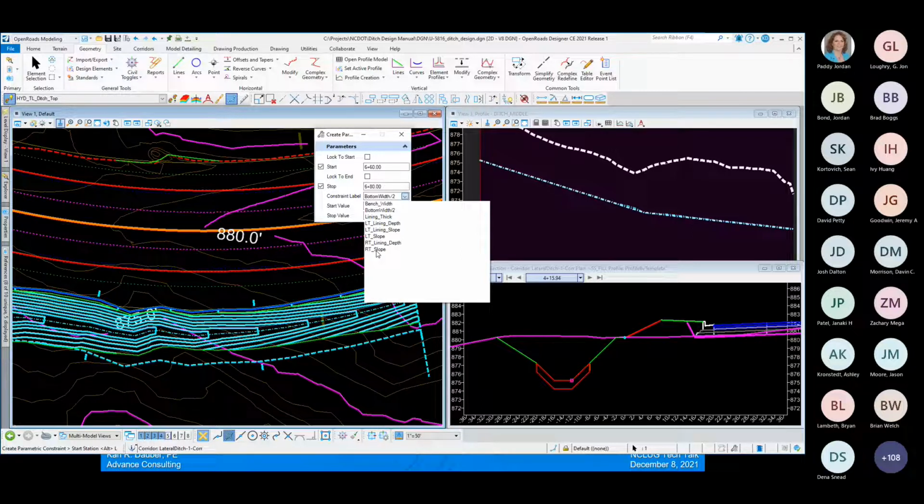The special cut ditch. If the special cut ditch is remaining with the roadway engineer to model, does the ditch lining need to be reflected in the roadway template? I think the answer to that is yes. The video that I have on my YouTube channel shows how to create the ditch controls, how the hydro staff would create the ditch controls, and then how the roadway people would use those controls to modify their corridor.